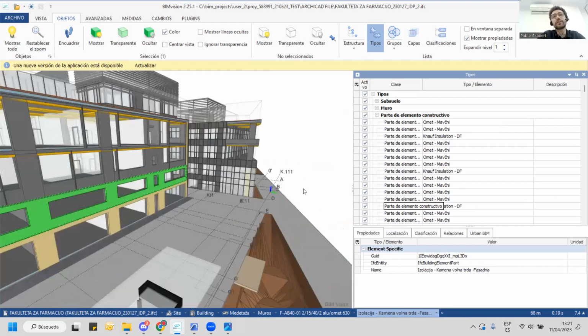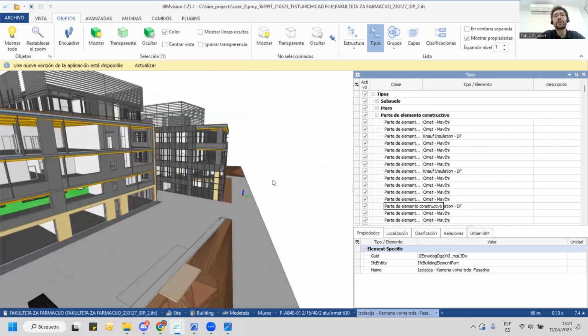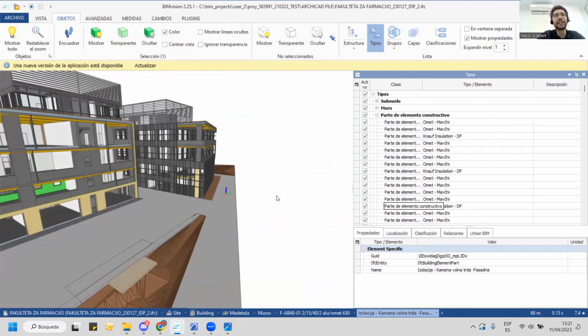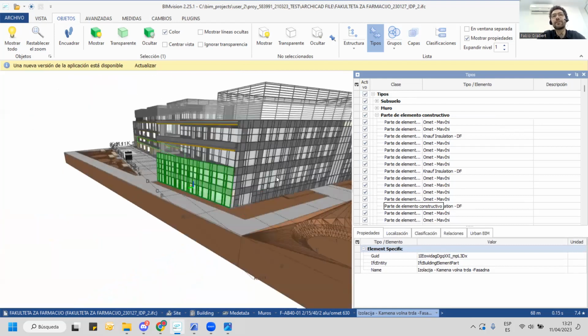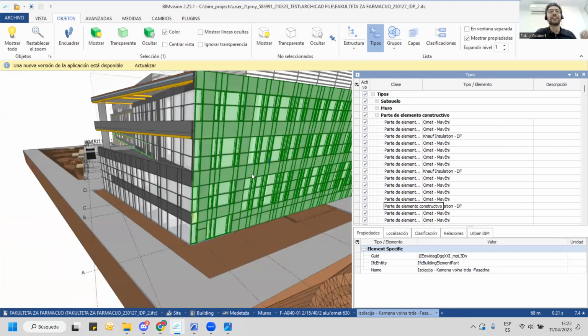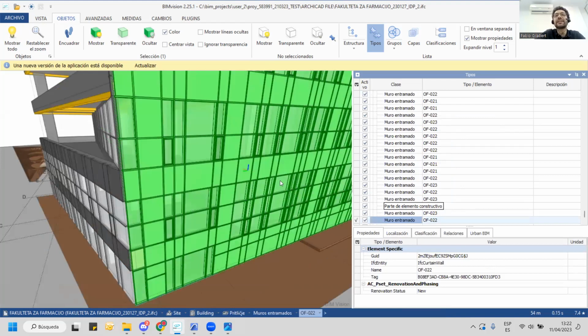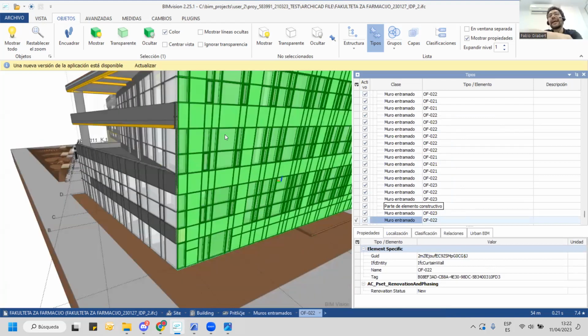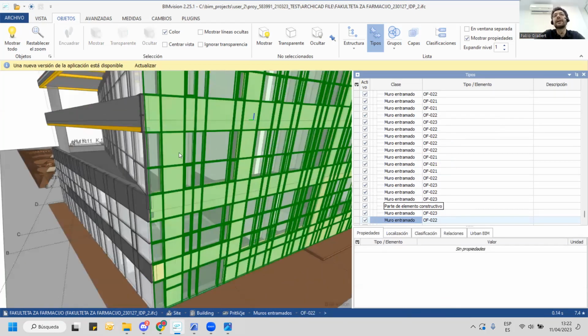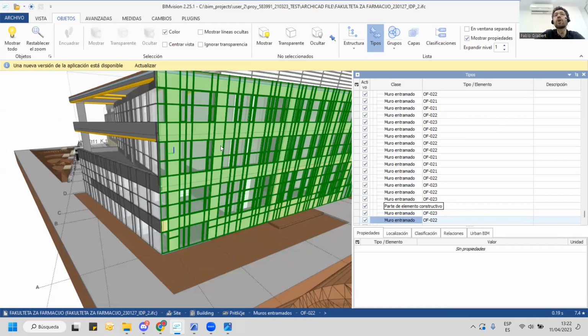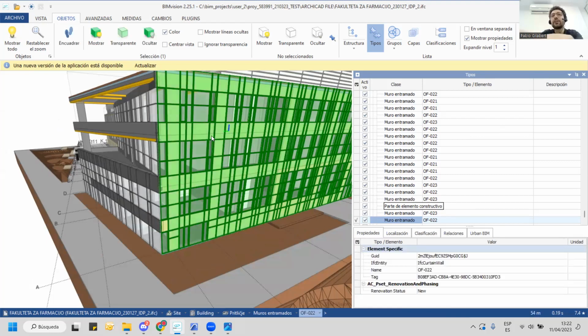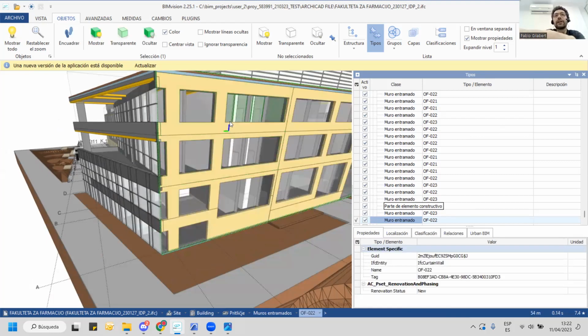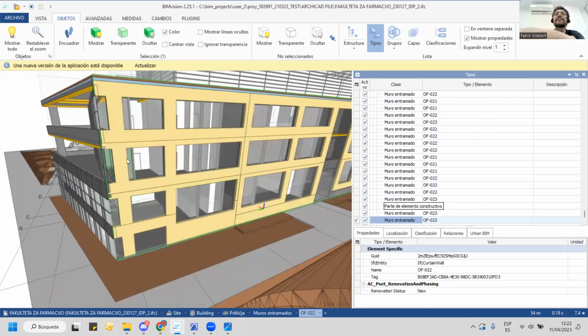Yeah, I'm not sure. Maybe your colleagues have a high level of knowledge in working with ArchiCAD, so I'm not sure. I think it's not really easy to generate only one element to define the envelope, but it's not a huge problem because OpenBIM analytical model will generate a basic energy analysis model with this information.